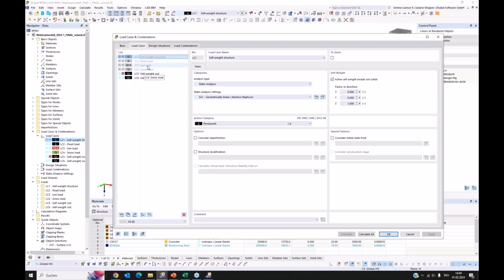So it doesn't make sense, if we take live load as an example, to only solve this live load case. There it would use the stiffness from 0 because we don't have other stress there. Before the live load is assigned and causes deformations, we already have self-weight of soil there, we have self-weight of structure there, and eventually dead load, and they all cause stress. From that, the correct stiffness comes, and with this stiffness, the live load should be calculated. So it doesn't make sense to calculate it alone.